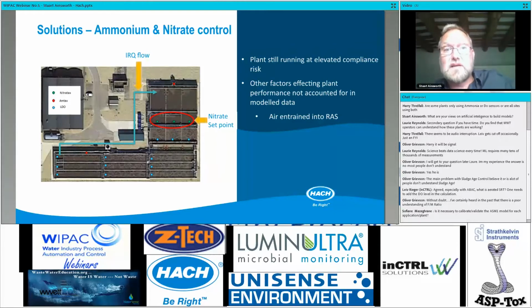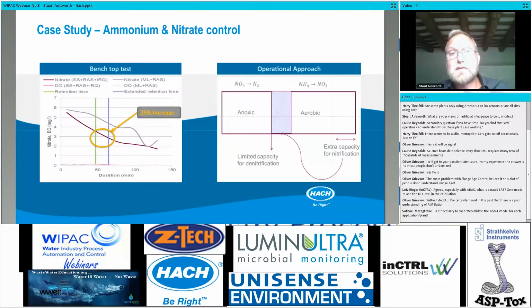Normally that would have been enough to get us past the post, but in this particular case, some of the work that went on at the same time with the return activated sludge meant that there was air being entrained into the RAS. So the actual plant behavior diverged from the modeled behavior because of this introduced air into the system.